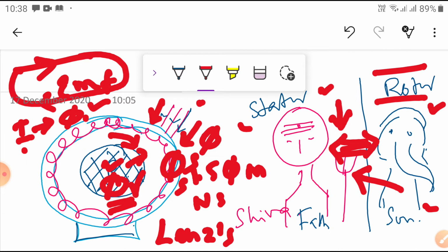Okay. So here what has happened? The current produced in the rotor conductors is such that it opposes the cause of its production. What is the cause? The relative motion between the stator magnetic field and the rotor conductors. So that's why automatically a torque is developed. Due to the torque, the rotor will rotate in the same direction as the rotating magnetic field to reduce the relative motion between the rotating magnetic field and conductors, as per Lenz's law. Then the motor is started.